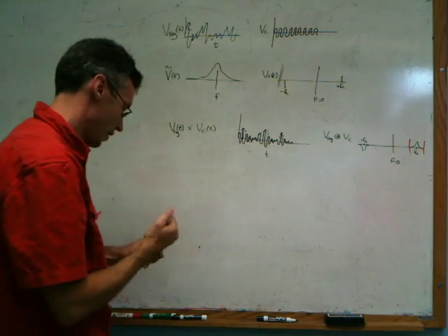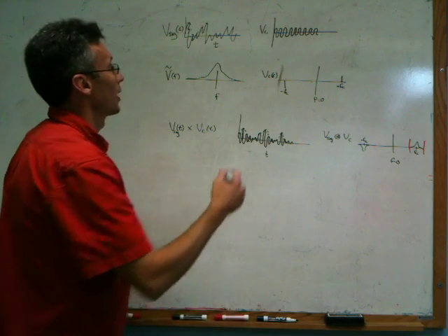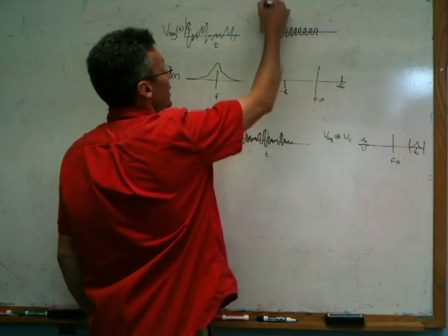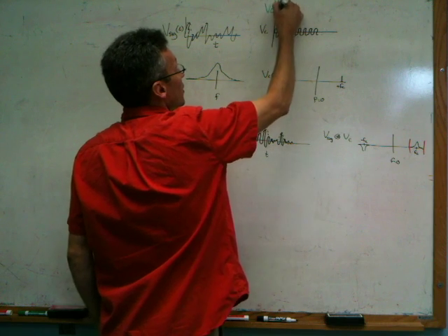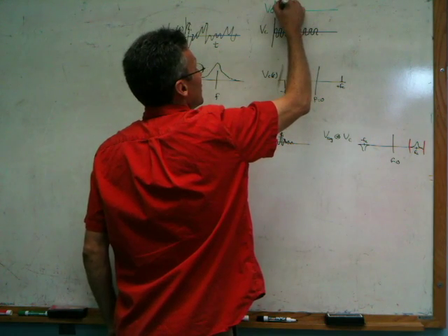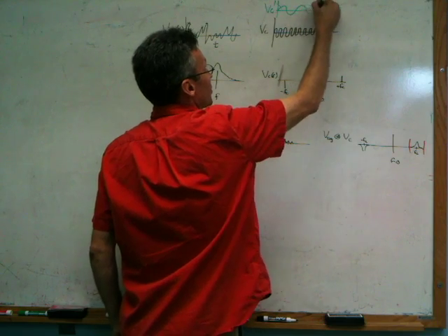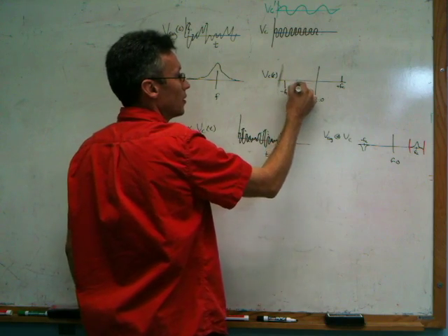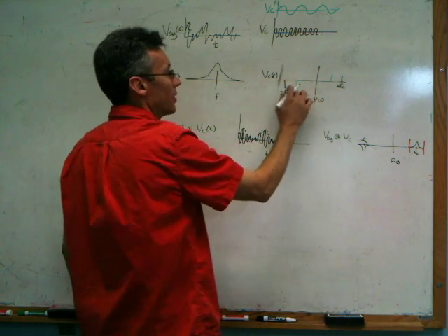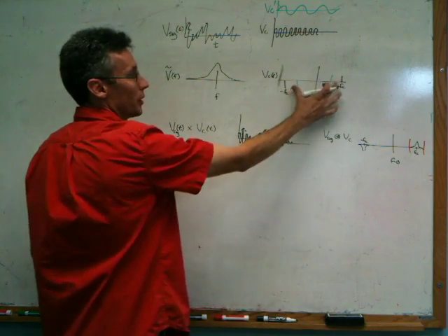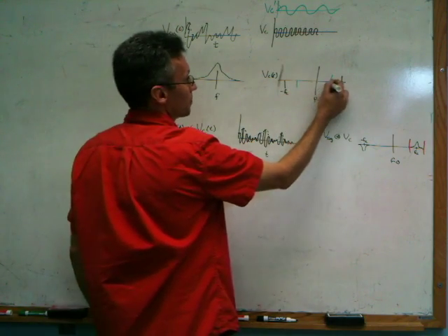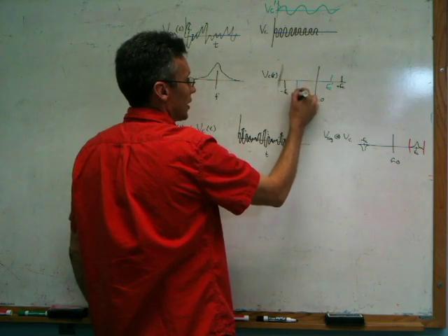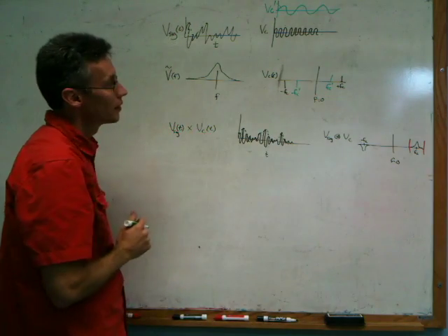And of course, the value there is that I can repeat this process with a different carrier that's at a different frequency. So let me consider, I'll sort of exaggerate this, but a lower frequency carrier is going to have the same frequency spectrum, but the center frequency is going to be less.